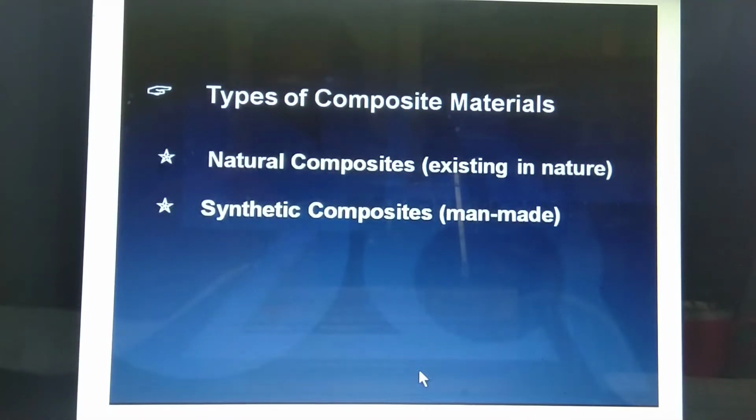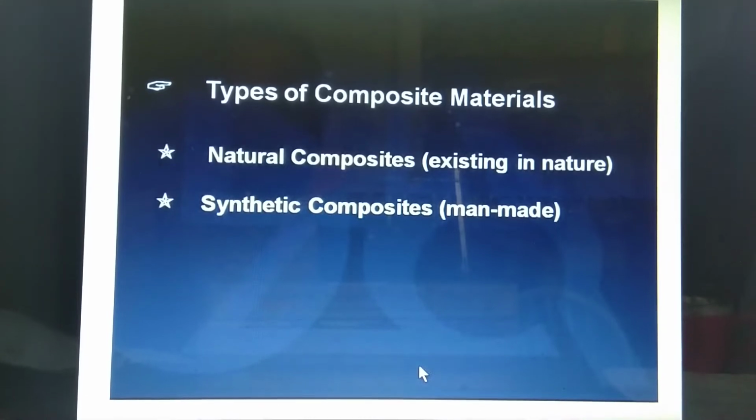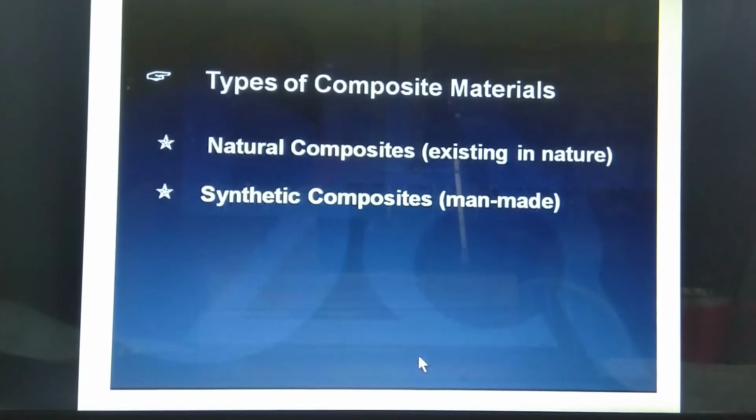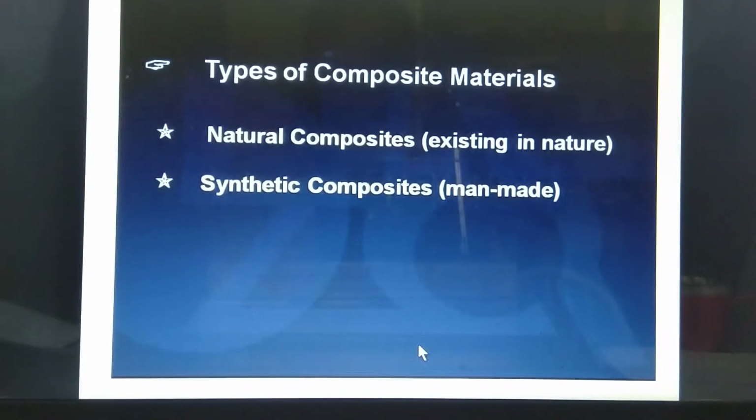Before getting into the types of composite materials, the polymers that are often used in composites are either thermoplastic polymers, thermosetting polymers, or elastomers. They are the source of a wide variety of low-priced raw materials which offer many advantages like low specific weight, high corrosion resistance, good electrical and thermal insulation, attractive optical properties, and so on. What is a polymer matrix composite?